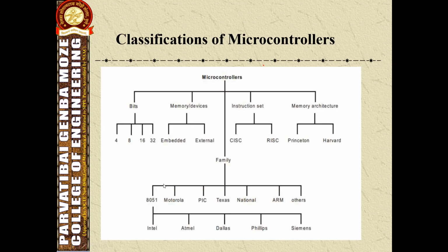It indicates that it can operate on 8-bit data at a time. The 8051 has become popular after Intel allowed other manufacturers to make 8051 with the condition that they remain code compatible with 8051. This has led to different versions of the 8051 with different speeds and on-chip ROM. All the versions are compatible with the original 8051. The 8052 and 8031 are 8051 family members.